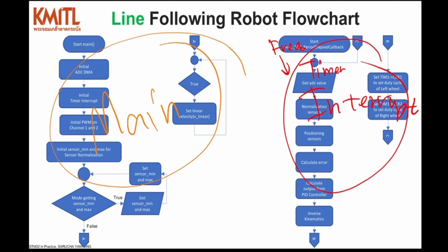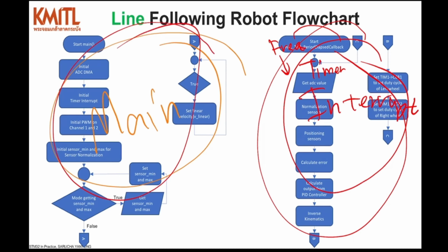We know this program will execute every maybe 10 milliseconds, exactly. The main program cannot do that. Someone thinks it can, but the timing is not strict, because it's not made to be strict like a timer interrupt.